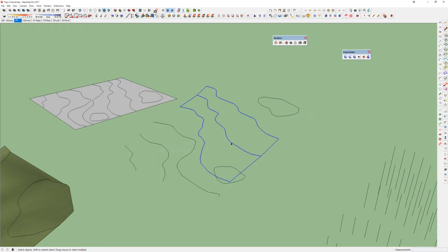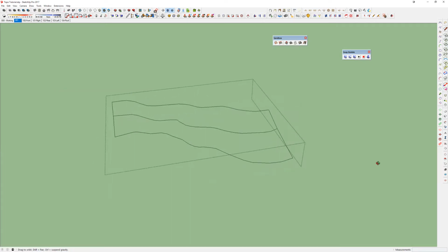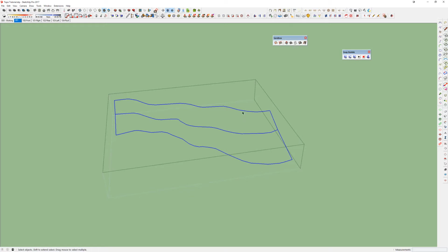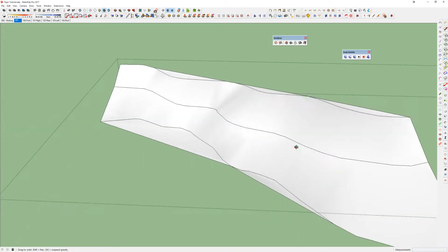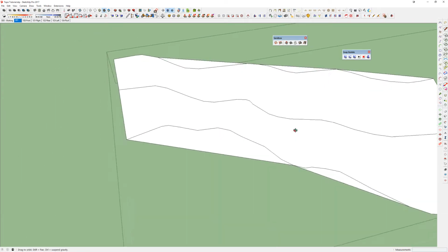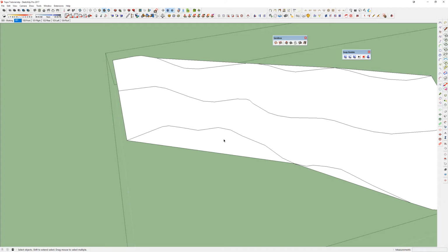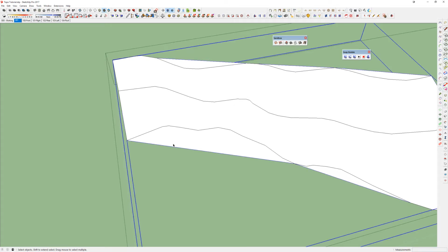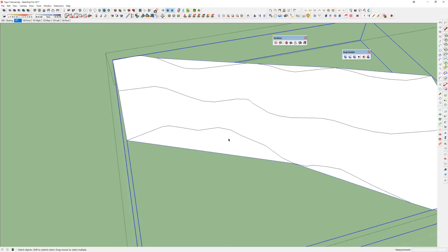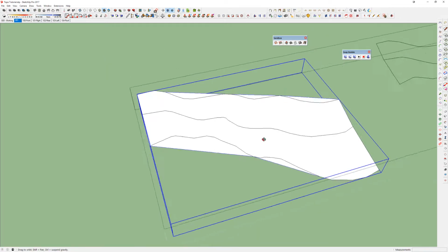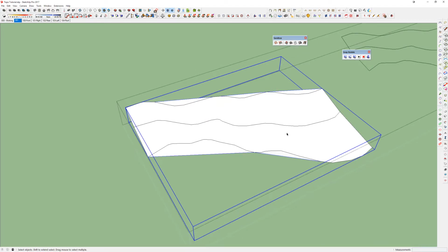So now I'm closing the loop. I'm just going to deal with these real quick inside its own group. So again, if I click here on the Sandbox tools, let me make a quick copy of this. You can see it creates the approximation. And one of the things to be aware of with Sandbox tools that sometimes is good and sometimes is not: you see it created this line from here to here, where if I go back to my actual contours, I didn't have anything there. So I don't necessarily want that. In some instances I may.